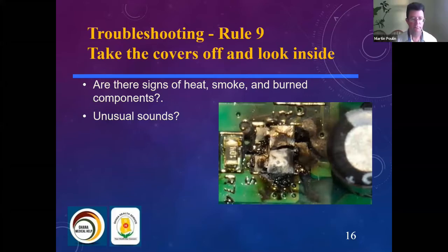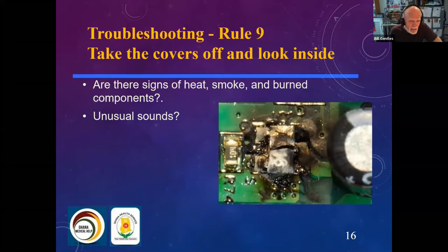Okay, you've done all your diagnosis on the outsides of the machine. It's time to take off the cover and look inside. Again, many of these troubleshooting rules require no knowledge of the schematic diagram, no knowledge of a technical manual, just using your eyes, ears, nose, and your intelligence. Are there signs of heat, smoke, burned components, unusual sounds? Often you can see or smell overheated components that will lead you to problems inside the device.